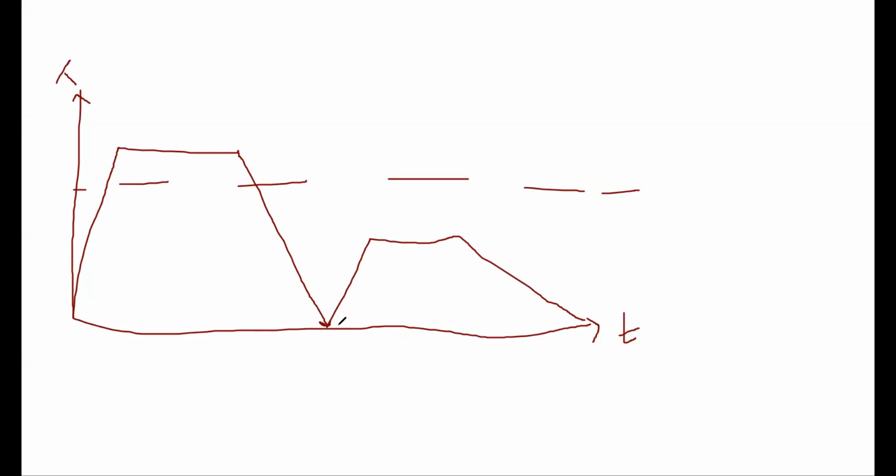Now in this tempering process, what you need to do is heat that cooled steel, the quenched steel, again. Right, once you cool down the hardened metal, as soon as it is cooled, you have to heat it again. Then you keep it and then you cool down here.